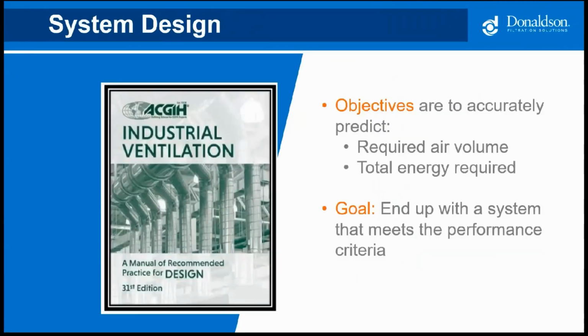In system design, we have two main objectives. We want to accurately predict the volume of air in CFM that's required to effectively capture and control contaminants at their point of generation. We also want to predict the total energy and horsepower required to produce those required airflows.